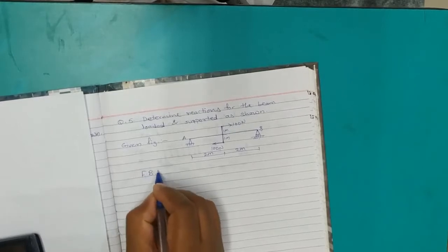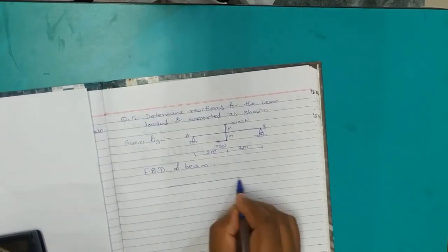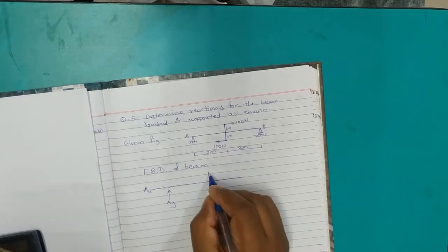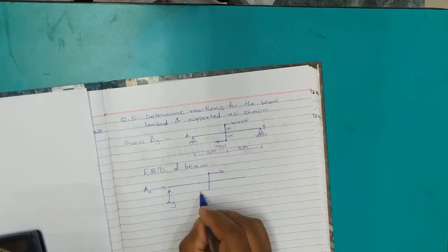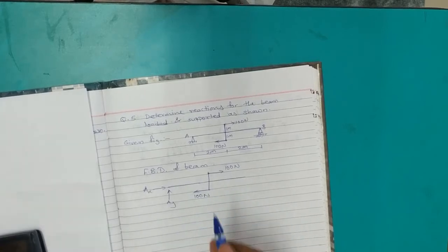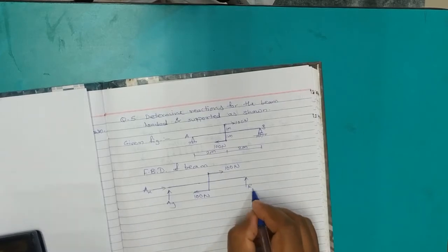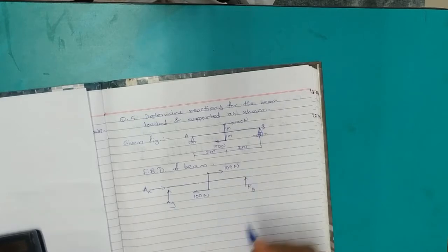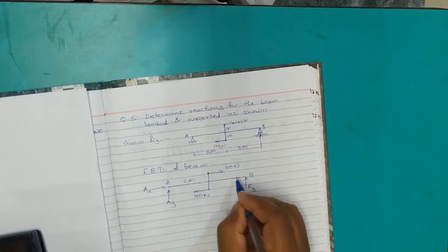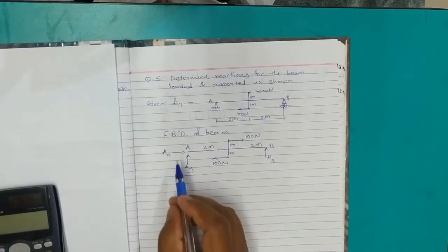First of all, as usual, let's draw the FBD. Now here, let's show the horizontal and vertical components of the hinge, AX, AY, and we have got this 1 meter arm extended vertically on either side, on the upper side as well as on the lower side, and at the end of that vertical arm, we have two horizontal forces, 100 Newton each, applied in the opposite directions, and reaction of the roller RB. Roller is placed on the horizontal surface, so reaction of the roller has to be vertical, always perpendicular to the surface. We will have a single reaction for the roller, that is well known, and the distance is 2 meter each, and the vertical distance for the arm is 1 meter each on the upper side as well as on the lower side. Let's solve this for RB first.